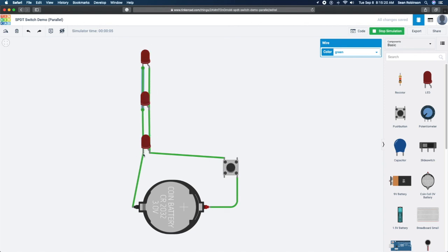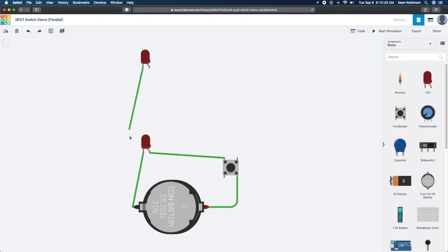because they're all connected. So you could take this LED here and delete it, and this would still be connected here. Or let me say that a different way. If this LED were to burn out and not work, this connection here would still be connected, and this light would still work.